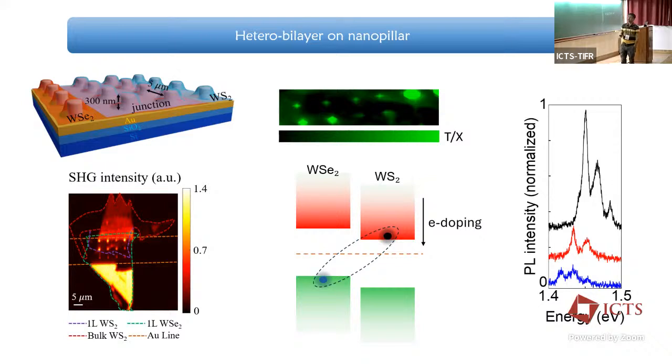Second thing is that we talked about the funneling. It's not just a change in the band gap. I've not done these calculations, but there are reports from DFT calculations which show that it's the conduction band that actually bends. The valence band more or less remains flat.